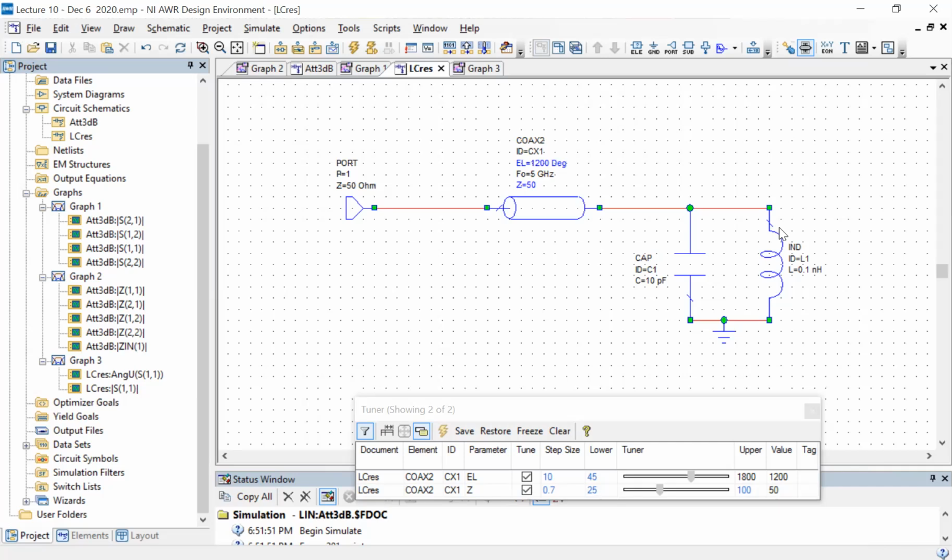The only real way, and in fact people often do this, is to first connect some device here whose properties are known, cool down, measure, warm it back up, change it, do it again. There are some tricks with certain devices you can play where sometimes this thing is composed of some active device like a Josephson junction, and you can pass a current through it and turn it into a resistor. If you don't pass a current through it, then it's sort of an inductor. And in some cases, there are ways to even turn it into an open, and people do this.